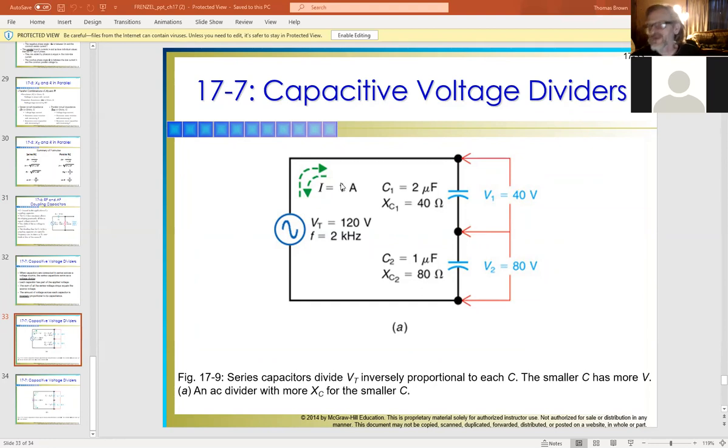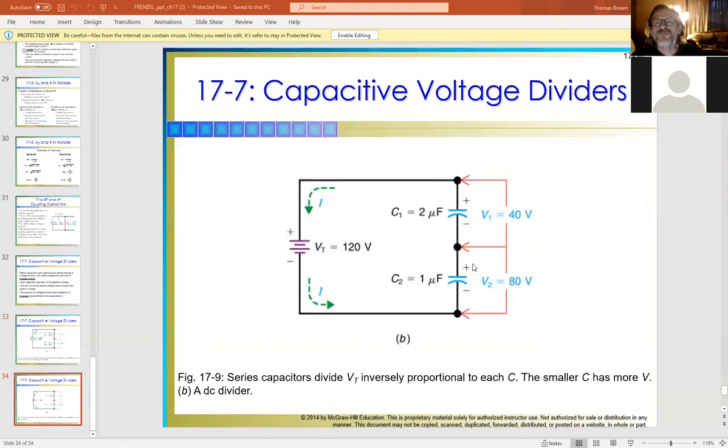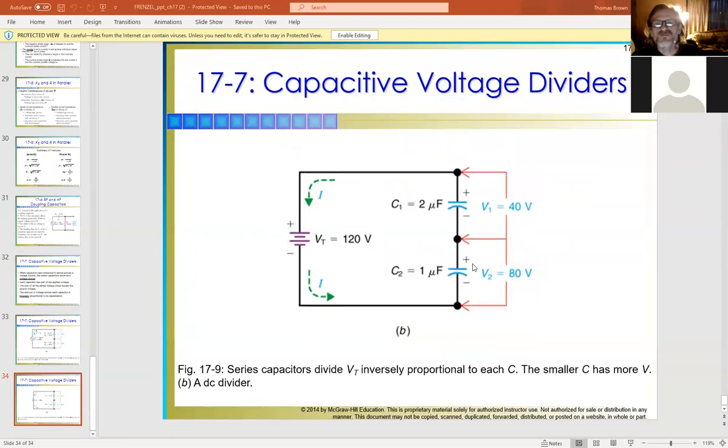And because current remains the same in a series circuit, we have an I total of 1 amp that gets applied to both of those and gives us our voltage in this case. Now, we can use the actual voltage divider, but he's basically making a statement and showing how the capacitive nature works and what we can expect.